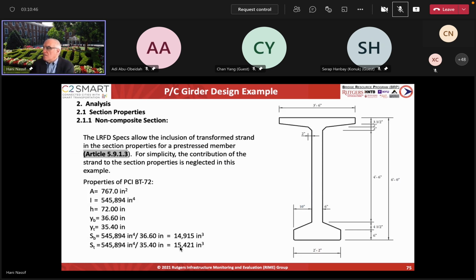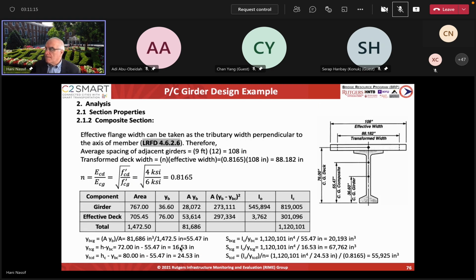And this is the girder. So we know what girder we are using. If you look at the PCI manual, or many books, they have this information. These are standard sections, about the 72 inches deep PCI. And there are the AASHTO girders, which are very similar, and those are popular because they are produced by the producers a lot. Sorry. So the first thing you want to do is, now we have the thickness of the slab.